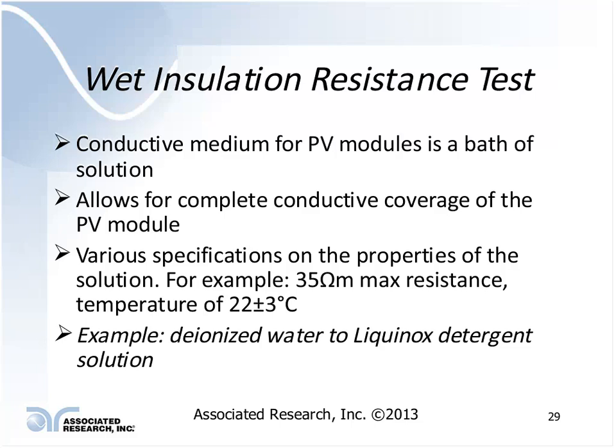How could you get this ionized solution or saline solution, so to speak? You need to break up the surface tension a little bit. Tap water actually has a fairly high surface tension. Like I said, it's not as good of a conductor as you might think. However, if your solution's saline or you break up the surface tension, you can get within these parameters. An example is, let's just say, deionized water with a Liquinox detergent solution, because detergent is a surfactant. It will break up surface tension. That's just an example of how you could create the solution to run this test.